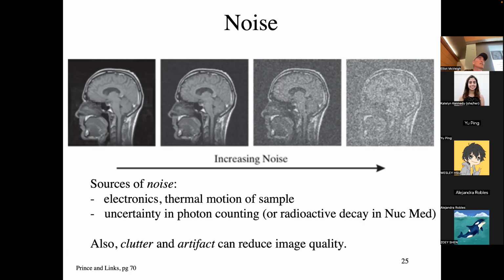All of those electronic devices have an internal amount of noise called Johnson thermal noise. If you take a resistor and put clips across it and look at a voltmeter, and there's nothing across there, you just keep cranking the amplitude, you will see there's a random signal on that resistor. It's just thermal motions of charged particles in the resistor. If you dip it in, say, liquid nitrogen, the noise goes down because the motion slows down. If you put it in an oven, the noise goes up because the thermal motion goes up, right? So that thermal motion, you can't get rid of that. That's always going to be in your electronics, right?